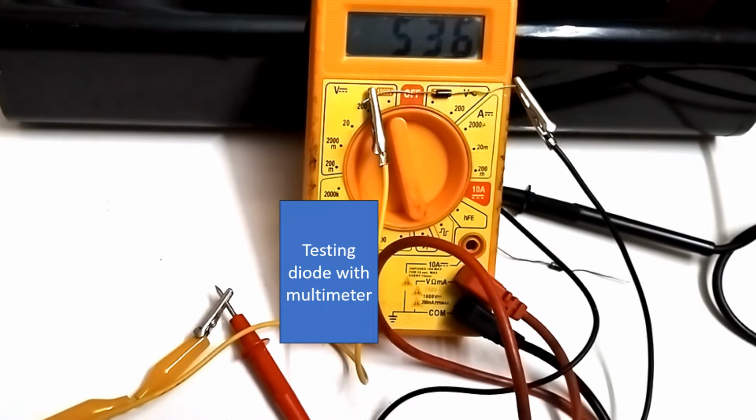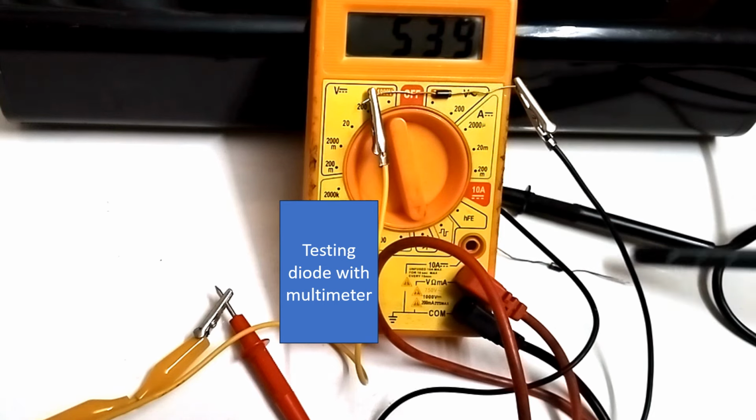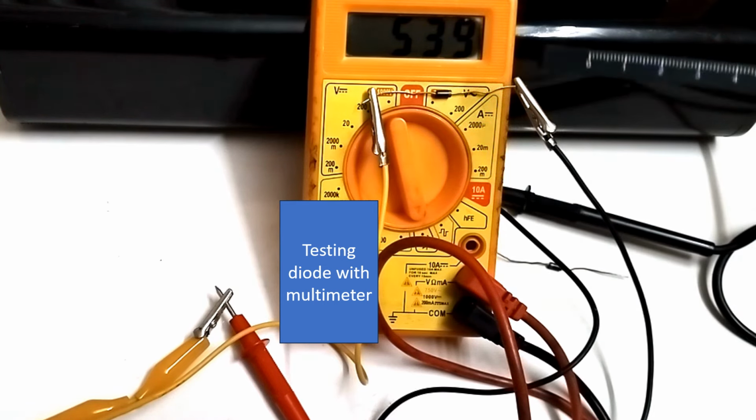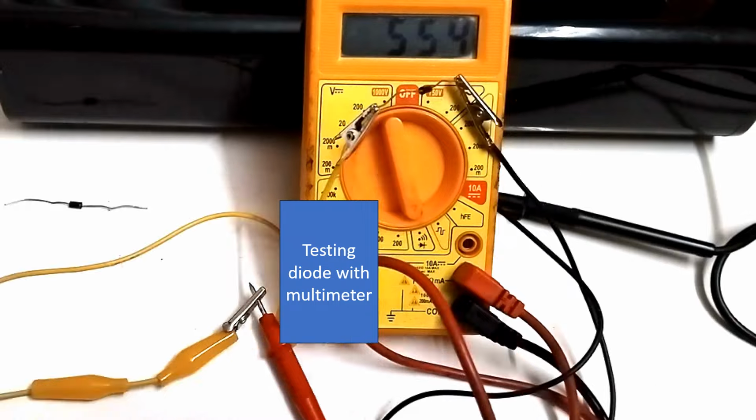Now I am testing another diode of the same type. You can see that there is slight difference in the voltage across the diode in forward bias condition. It is 538 millivolt rather than 555. This was the diode which we tested initially, and this is another diode. There is slight difference. Such variation can occur from device to device.